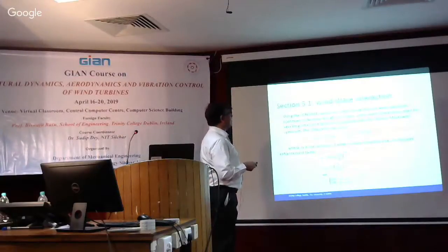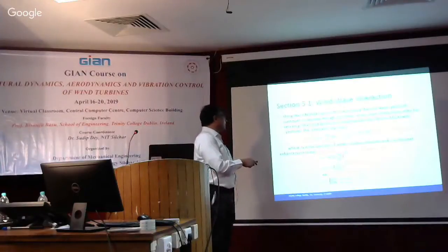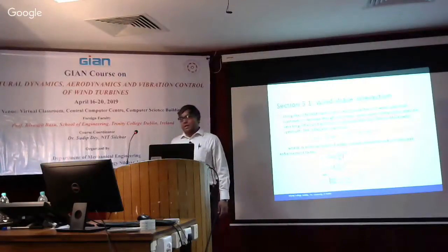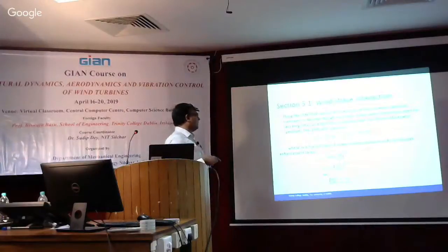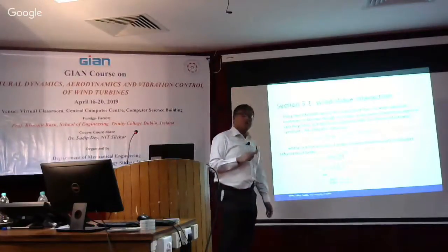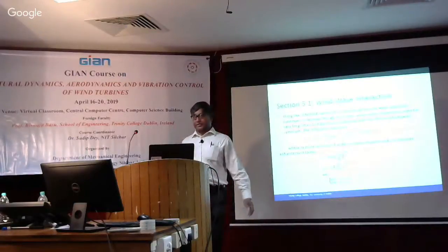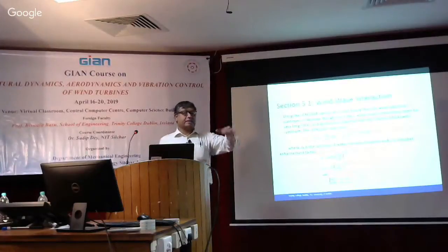This is important because alpha is a function of U10, meaning the wind velocity at 10-meter height. So this is one way to account for the wind in the wave spectrum, though not fully, in the sense that the wind actually generates the wave. When the wind blows, it excites the surface, waves are generated, and slowly they build up.